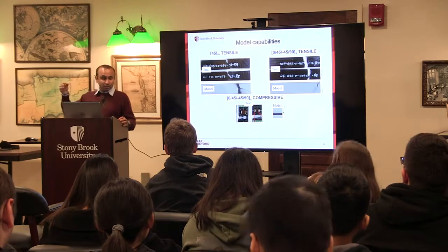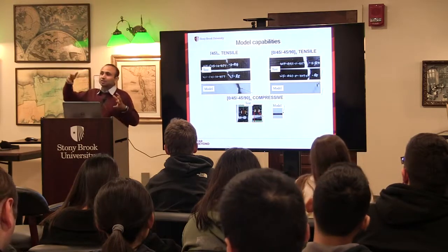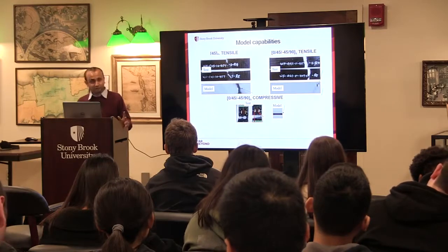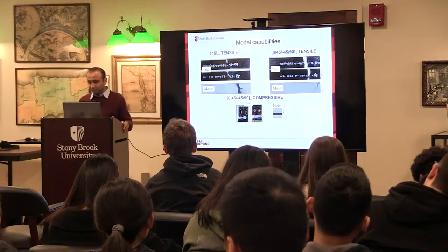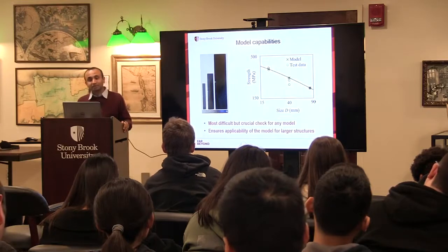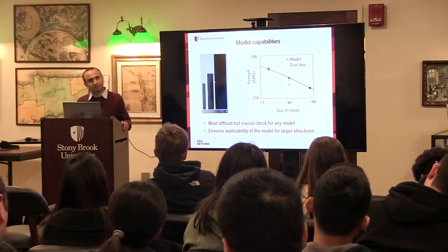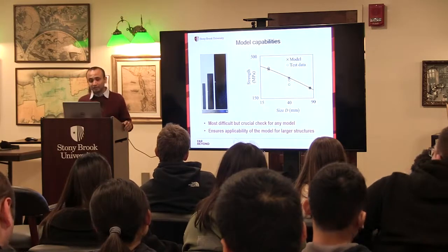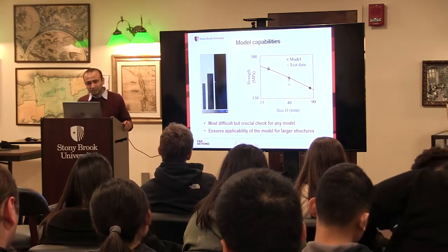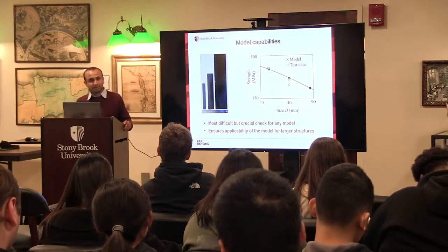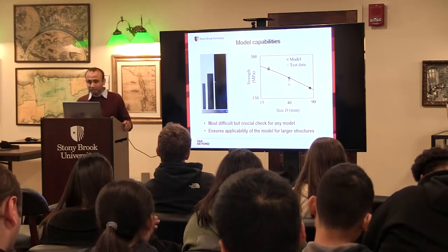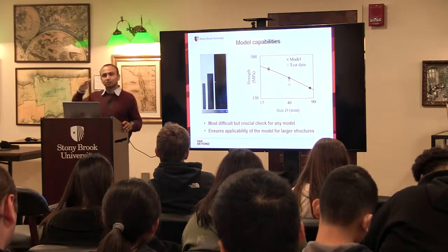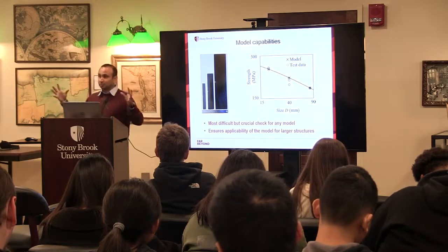It doesn't explicitly model the crack, it just models the material becoming less stable. And you can see that it is fairly effective in predicting this crack. Mainly it predicts the size effect that I mentioned: how the material becomes more and more brittle, the model can actually capture that. These circles are test data. On the y-axis there is strength, and on the x-axis there is the size. The model automatically captures how the strength drops as the size becomes larger.